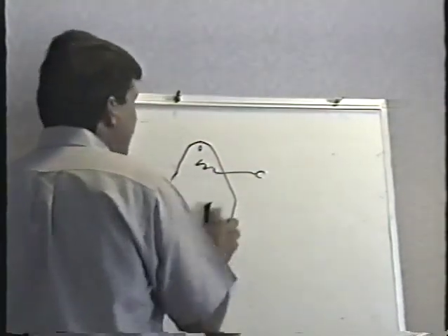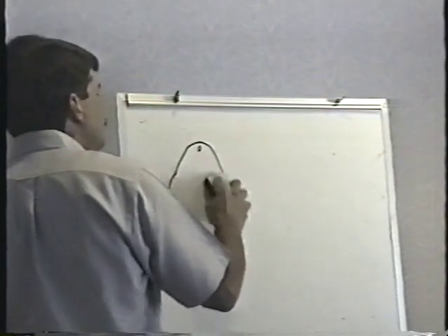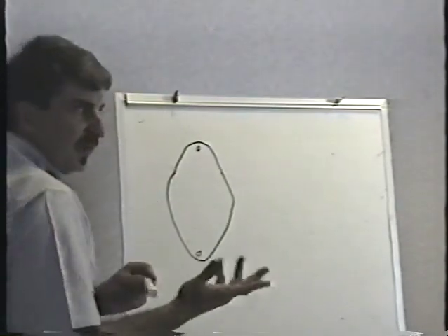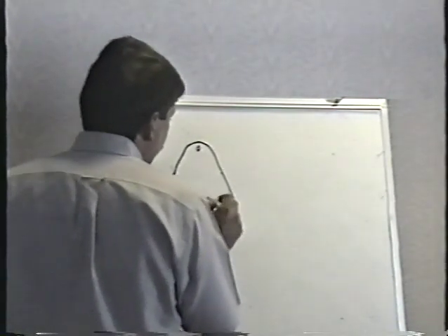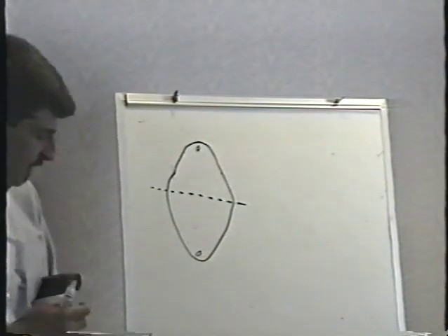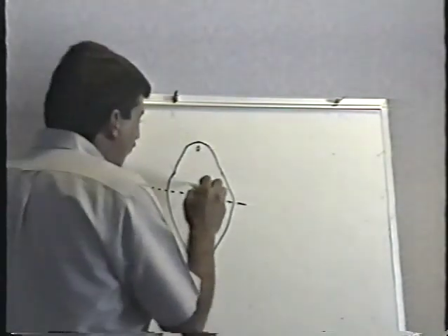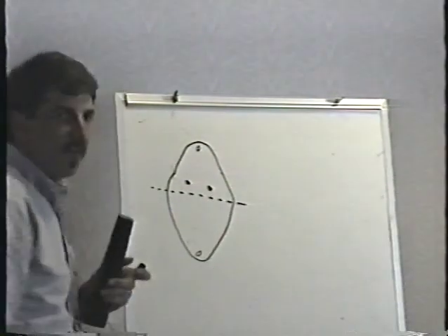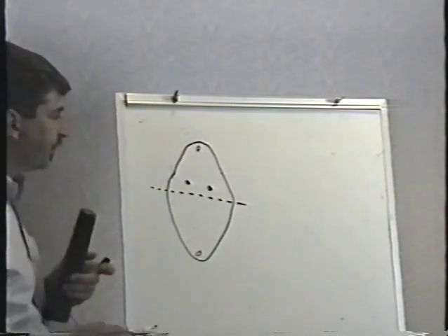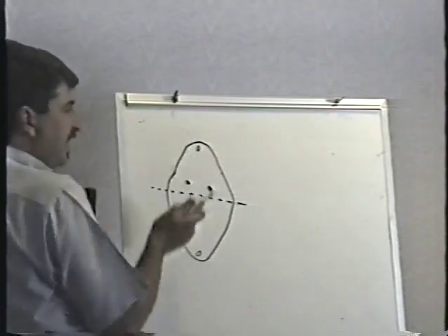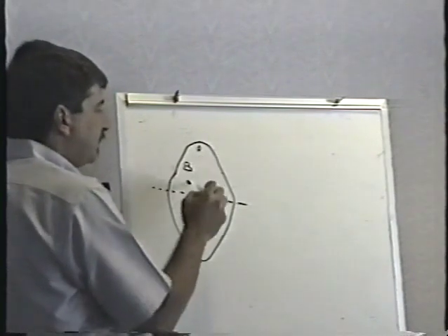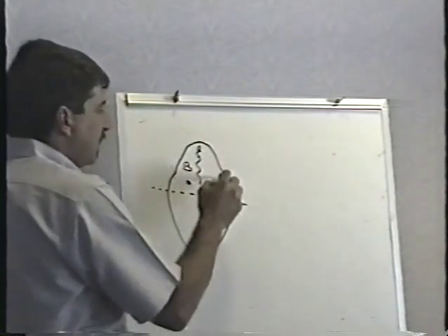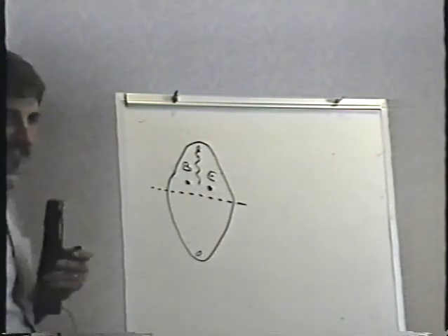Now, even though it's printed like this, you do have to know which lead is which. The way I normally tell is that if you look very carefully and draw an imaginary line dead center in that transistor, you'll see that those leads are not right on center. They are slightly offset. If I hold the transistor so that the leads are slightly offset above the center line, they're in alphabetical order. Base is on the left, the collector is the case, and the emitter is on the right. That's the way I remember it.